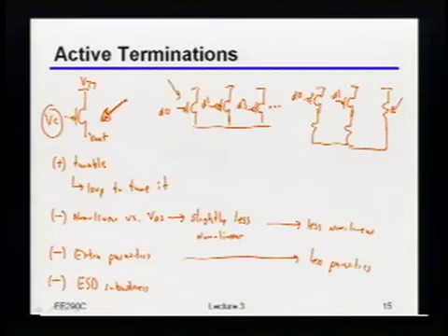Question? Yeah, so what's the benefit of having a resistor in series in each of those legs? Ah, okay. The first one is actually related to ESD protection, which is just that I don't have anything directly sitting on the output pad. That's not a huge deal. The other is that if these resistors are slightly more well controlled than the transistors, then in terms of the dynamic range you need to cover in the variation, it's a slightly better dynamic range here.